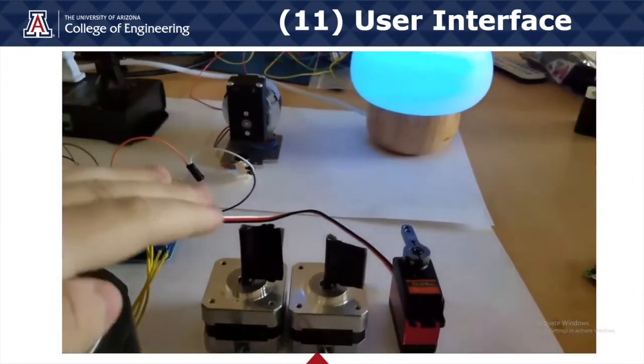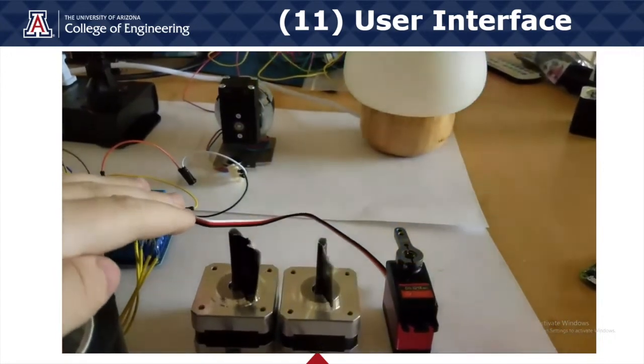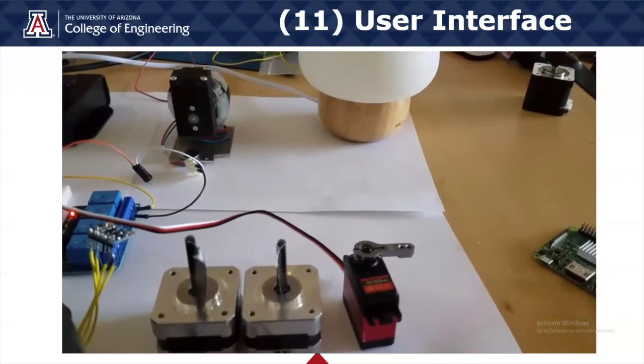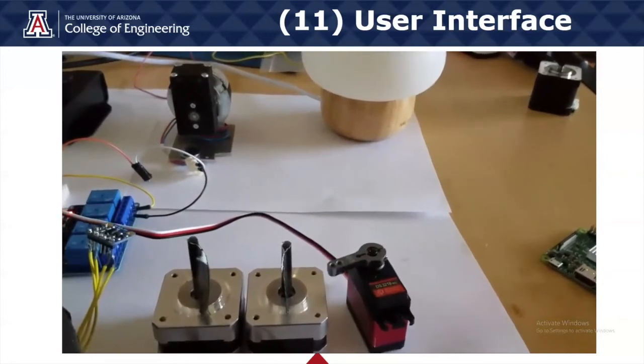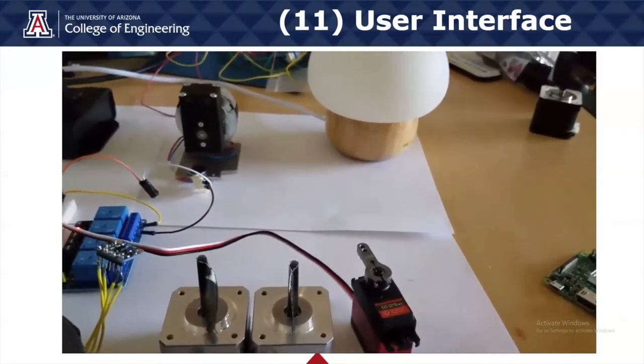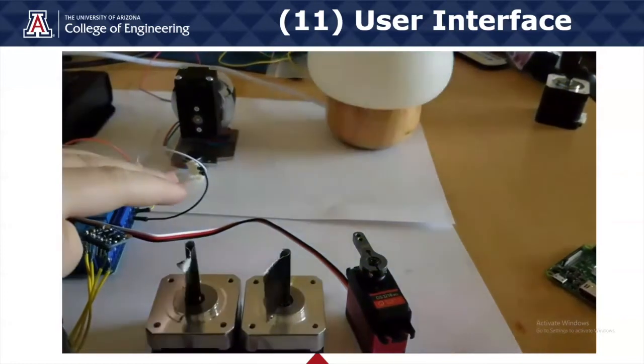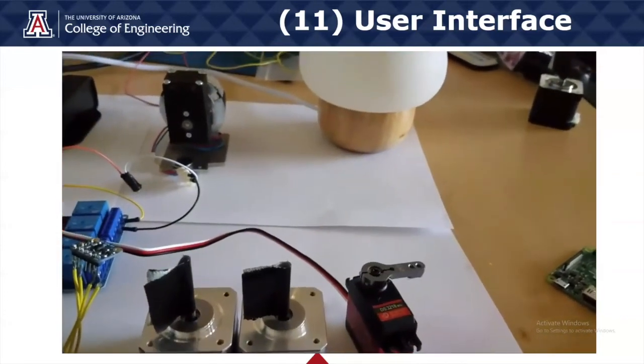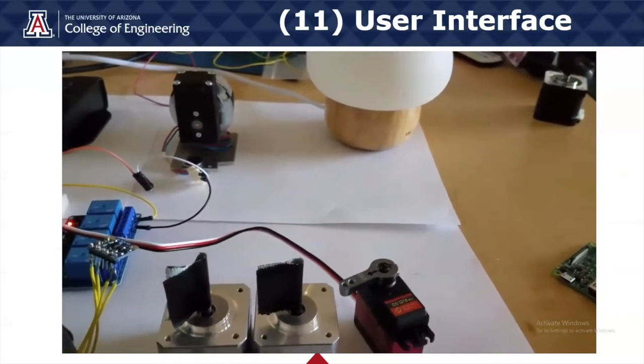When my hand, or in the case of the real system, an iButton rests in front of the sensor, the feeder bowl or light as seen here turns off and the motors begin to work. The servo moves from one position to another. This shows that the pick and place, which will be shown in more detail later, can go from the feeder bowl rail, grab an iButton, and then place it on the sticky pad.